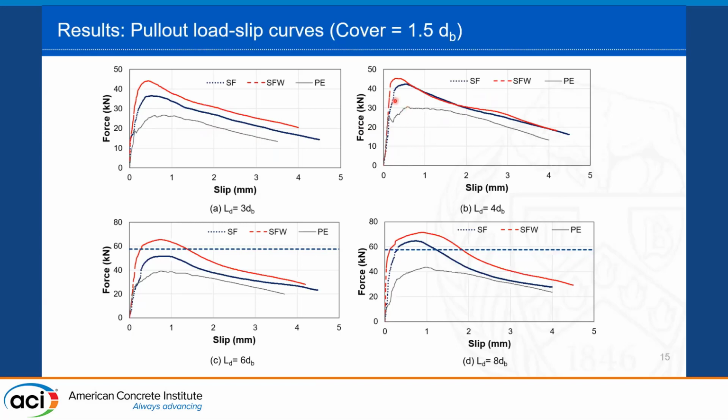And after that, the crack starts to happen and the fibers start to bridge the crack and show some hardening behavior until reaching the peak, and then the strength drops. For the case of PE material, here it shows the linear behavior until 50 or 60% of the peak strength, and then the cracks form earlier. And here the strain hardening behavior appears by forming multiple cracking until reaching the peak, and then the strength drops.